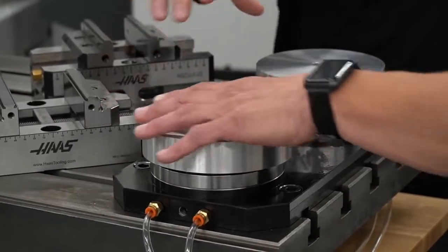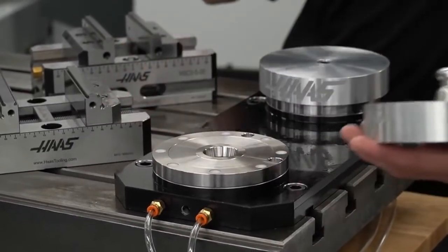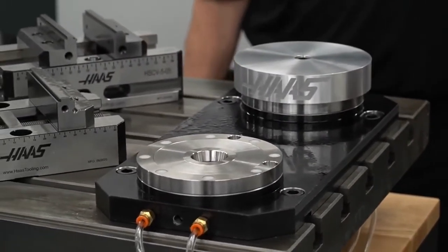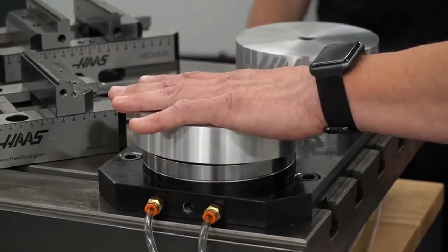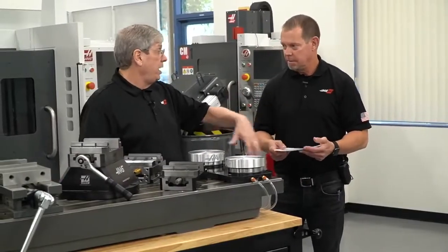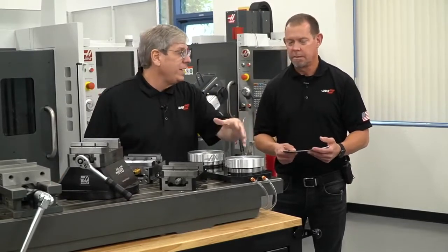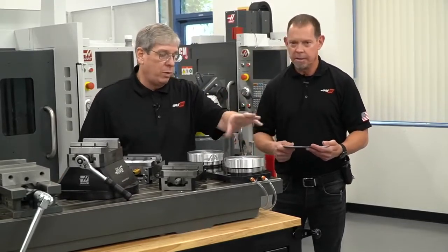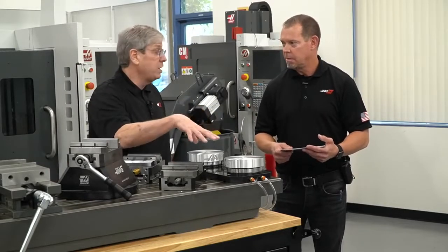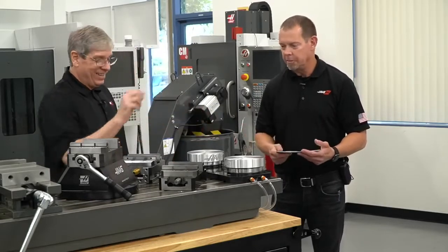Okay, let's pull this pallet off. Most people know, but just in case. So super quick, yeah, to your point, you got a fixture to pallet, and clamping it is as simple as that. You're done. Pull that pallet off, you can take it to another machine, and you don't have to indicate it in, you don't have to pick up the zero-point if that other machine has been calibrated, or your work offset has been set to the center. To the center, yeah, right.